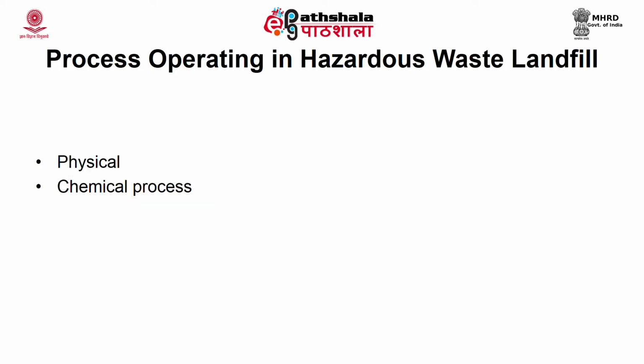First, we will see the process which takes place inside a hazardous waste landfill. Now, hazardous waste, as you all know, will have very minimum or almost negligible biodegradable waste. The waste which comes inside a hazardous waste landfill will contain one or more of these properties: corrosivity, ignitability, toxicity and reactivity. So, such waste cannot undergo any biodegradation. Then what will be the other processes that take place inside the hazardous waste landfill?